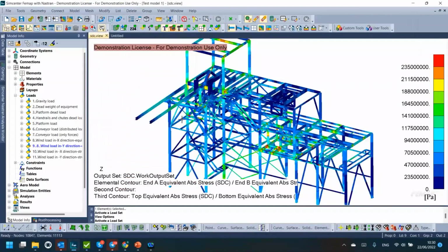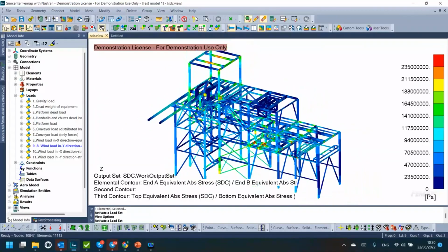The idea is that you compare the resistance of your cross-section and the member according to Eurocode compared to the forces which appear under these loads. So your actual forces, bending moments, shear loads, all these kind of things are going to be compared with the actual resistance, bending resistance, and also buckling check done on top.